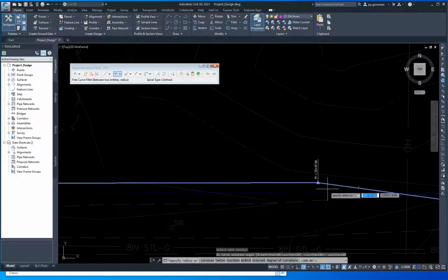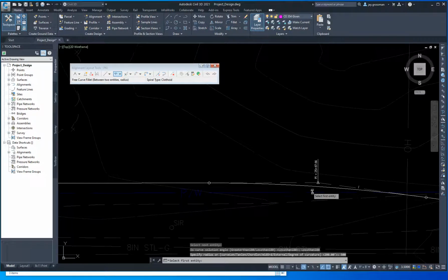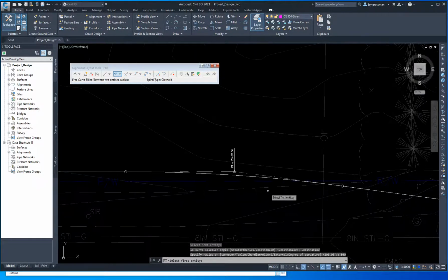Well, based on your design speed, you know what horizontal curve radius you need to use. And I don't know what you picked. I'm going to just pick something. So I'm going to pick 500 feet. This is in imperial measurements, so it's in feet. So there it goes. Oh, look at this. I got my own little horizontal curve, dropped it in.